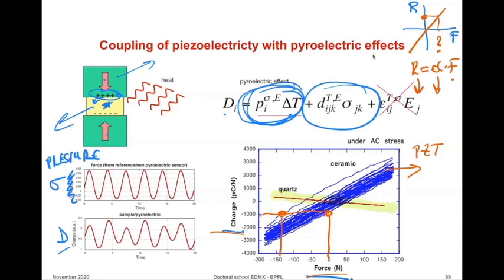The experiment is done under exactly the same conditions as the first experiment with the PZT. And here there is neither drift in this direction, nor this hysteresis that you see in a PZT. So why is quartz giving us a nice straight line, ideal piezoelectric effect, and PZT, ferroelectric ceramic, doesn't?